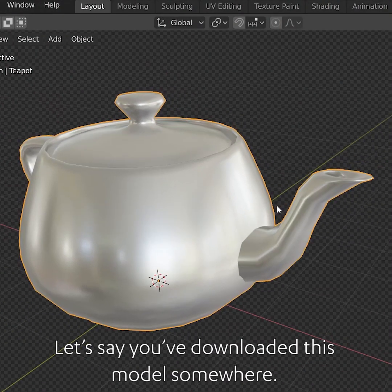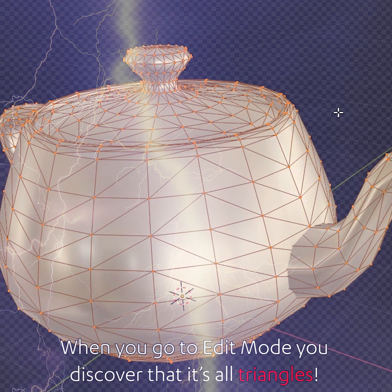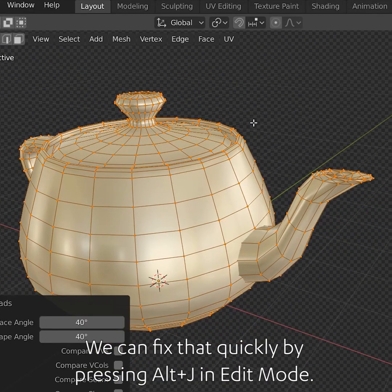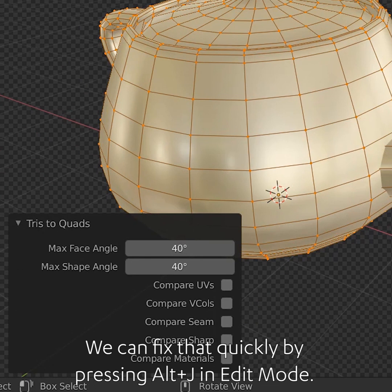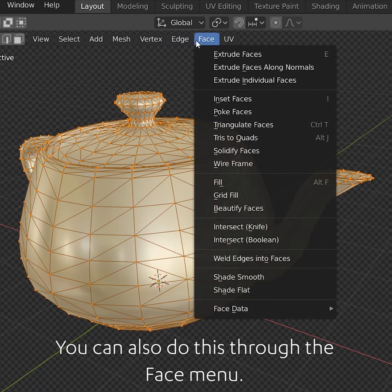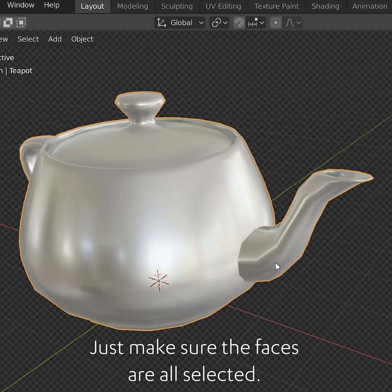Let's say you've downloaded this model somewhere. When you go to edit mode, you discover that it's all triangles. We can fix that quickly by pressing Alt-J in edit mode. Now it's all quads. Whew! You can also do this through the face menu. Just make sure the faces are all selected.